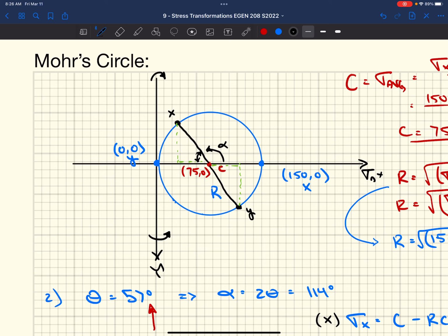And that's the beauty of Mohr's circle, and that's why I try to teach it this way. Even for me, in practice in industry, I have used this where I plot points and figure out what our principal stresses are, because it's easy to see. Instead of blindly using equations out there that you could just plug in and that should give you sigma 1 and sigma 2, and the maximum shear stresses, you can visually look at it, make a triangle, and figure it out with geometry.